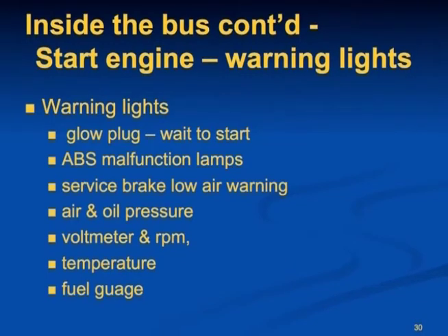And finally, the fuel gauge should indicate a safe margin of fuel for the day's operation. Every effort should be made not to let the engine read less than a quarter of the tank of fuel. Homeland Security recommends half of a tank, as we may be first responders in an emergency.